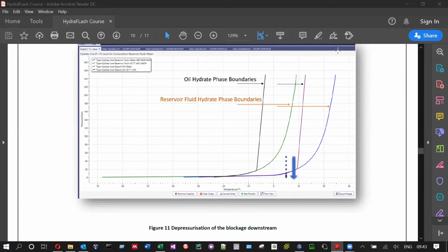I should tell you, from a design perspective, when you are designing the amount of methanol, how much methanol they need, they assume a 3 to 5 degree safety margin. And then they assume non-equilibrium distribution of methanol, so they add a percentage for that.